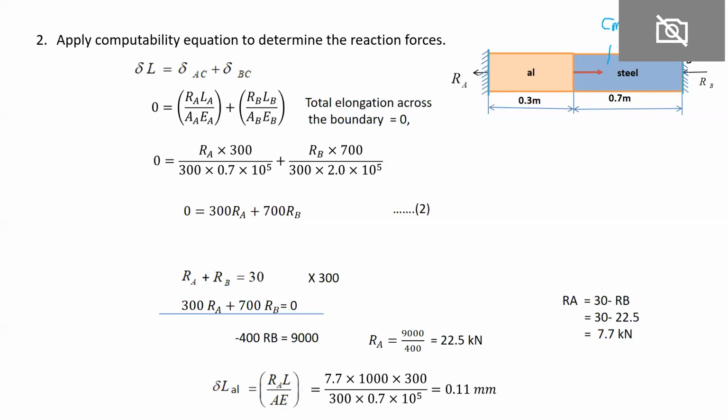It will undergo deformation definitely, but how much will it deform? Say this is the amount of deformation that has occurred due to the application of compressive load, and the same amount of deformation occurs in the aluminum material, because it is subjected to tensile load, meaning it elongates while the steel compresses. The elongation in the aluminum bar is equal to the amount of compression of the steel bar. So you can represent this in any way.